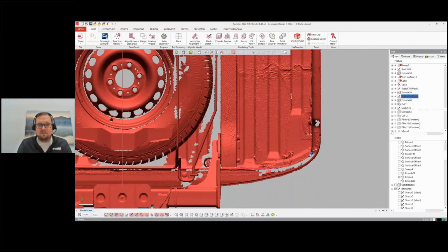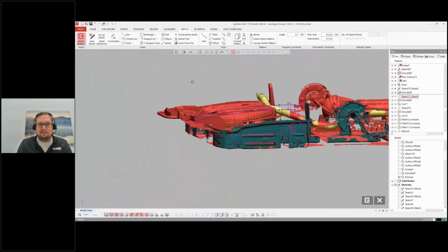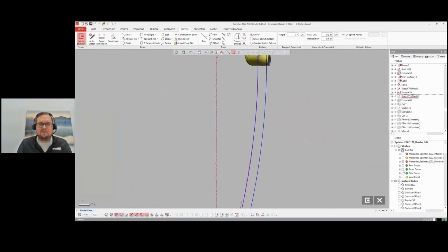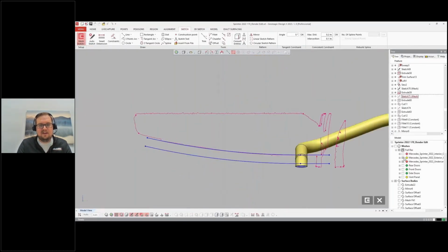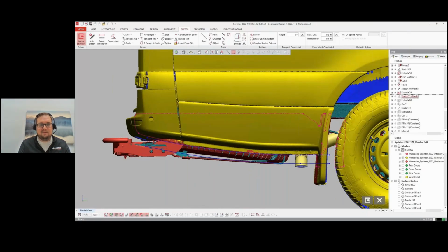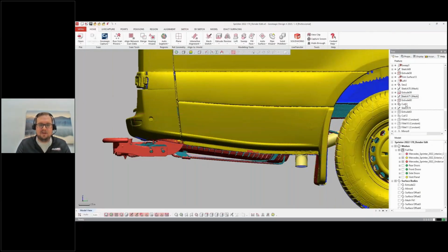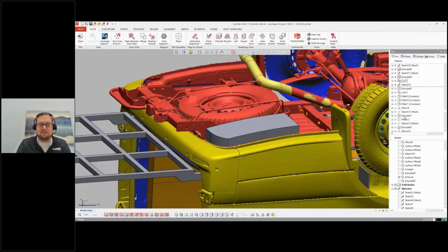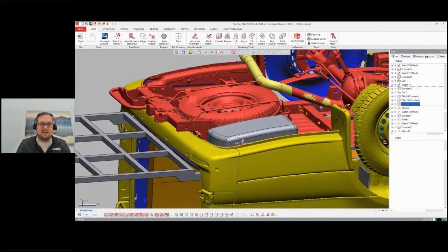I'm also making sure that I'm clearing bolts, I'm clearing features, and I'm using the side profile of the van here. So this profile is a sort of unique Sprinter look, it tapers up at the end. And I wanted to mimic that, but dropping it down to the same level as my spare tire here. So when I do that and use this feature to trim off the bottom of my water tank, once I get it put into place here, we're going to clean this up and do a quick little fillet and things around the end. So this would be like a roto-molded style plastic tank.